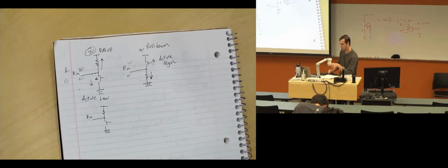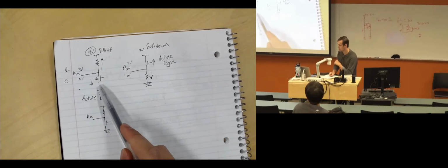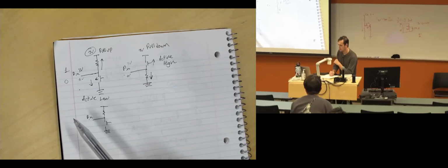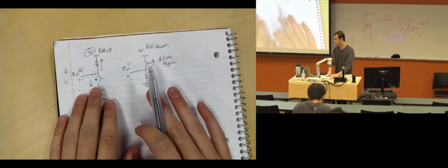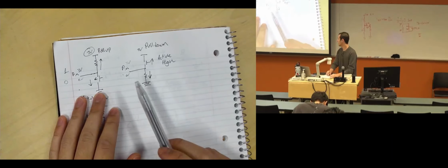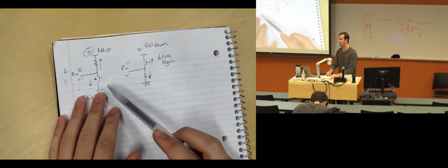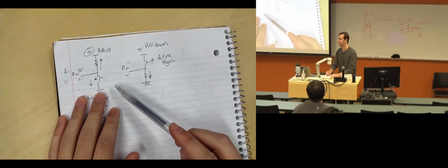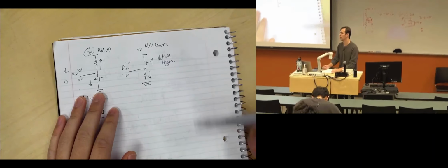The only way that works is if there's some sort of switch or button that switches the voltage onto your pin. So it'll probably look just like either of these. And you just have to look at, again, when it's not being acted upon, what is the default value, and whether that's pulling it up to high or low.